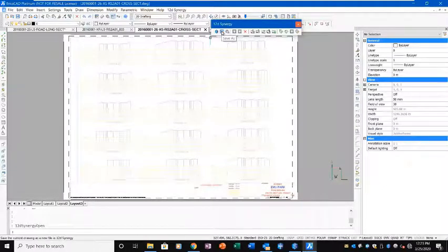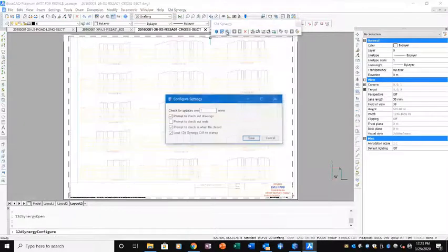The second button on the toolbar is Save As. So if you're creating a base and you want to save it as another drawing, you can do that from here as well. And the third button there is our settings. So there's the interval checker timing. There's the prompts to check out drawings and check in when closed. There's also a prompt to check out Xrefs. So if you open a drawing, it can prompt you to check the Xrefs out as well. And generally, I leave that one unticked. And then there's the system setting that loads the CUI when you open a drawing as well.